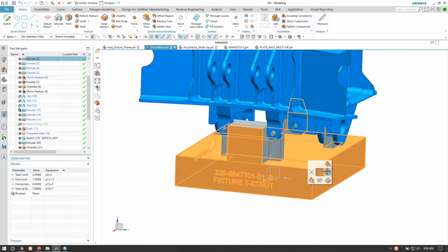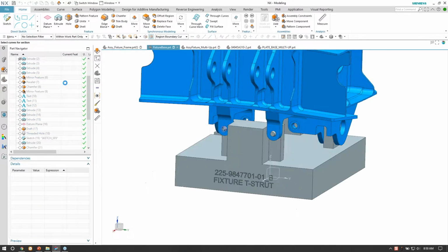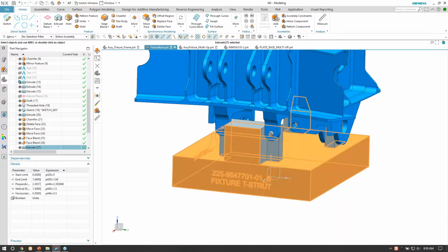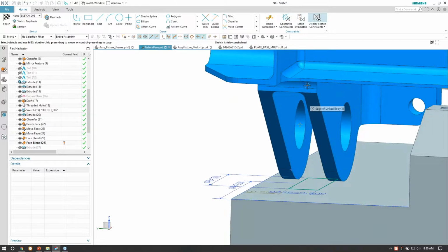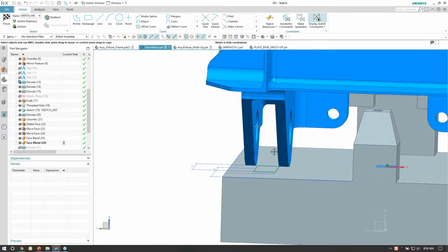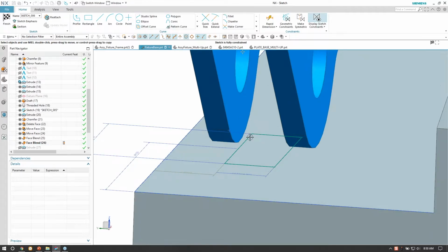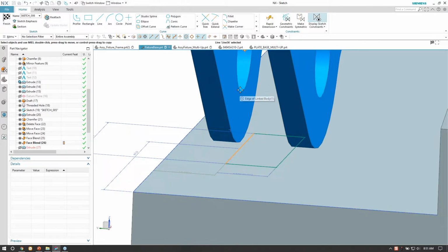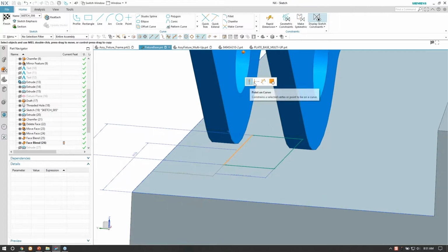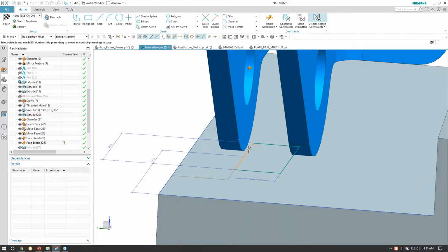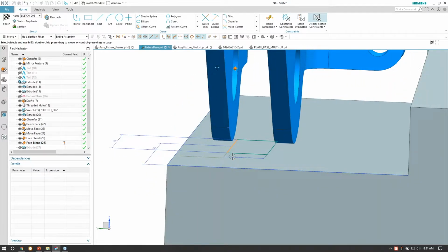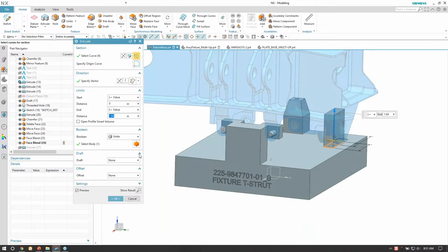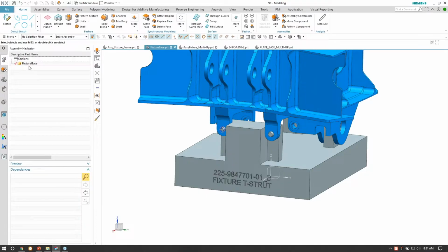So when I created my part file, if I take a look at this little tower back here, I tied my sketch to the geometry of the linked-in geometry that I've created. So if I go in and make another constraint, I can create like a point on a curve constraint. So I could tie this curve to this point right here, and if this face were to change, the size of my little sketch here will also update and move around. So I'll finish that and go back up to the parent.